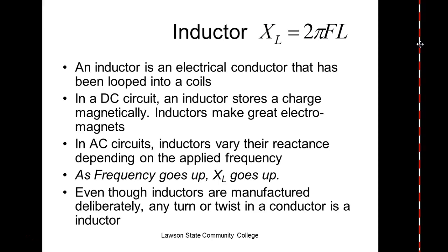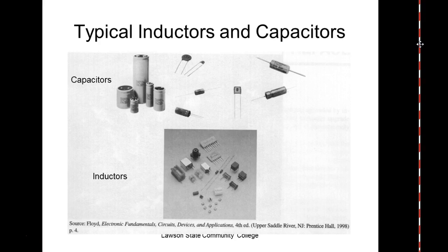So this means we have to be really cognizant of the placement of conductors, because if they get in close proximity together, that sets up a capacitor. If we put loops in it, it sets up an inductor. And of course, DC has no difference. So we can loop a DC conductor as many times as we want, and all we're doing is changing the R of the conductor. The more length we use of a conductor, R goes up.